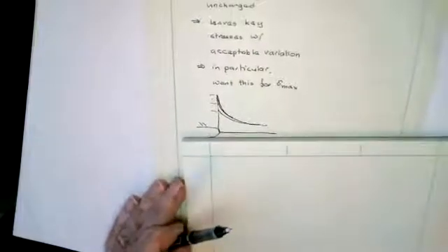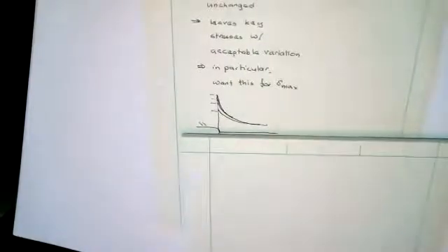Yes, if you do CFD, you refine your mesh in CFD. CFD typically doesn't use FEA. In CFD you have time dependence. You could use FEA for steady flows, but if it's computational fluid dynamics, you really have dynamics in it, so you have to use finite differences to handle the time variable.